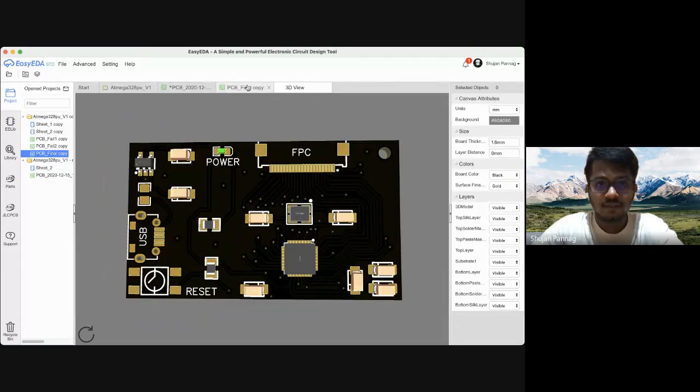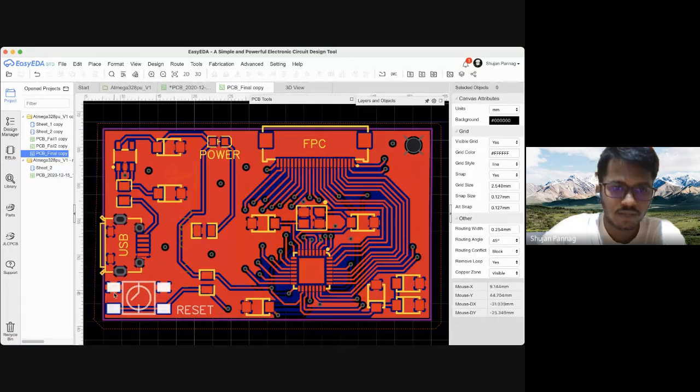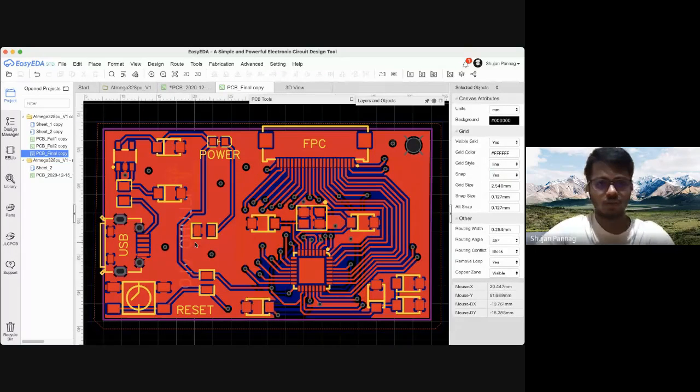And another thing, I've done a really poor job, even though it's one third the size. I've left a lot of space right here, so you can reduce it in your own versions of Arduino. I was talking about the size of your components, right? You need to find a smaller one. I've used 3216. Probably the best would be 0805 or 0402, which is really small and could be the same size as your copper tracks.